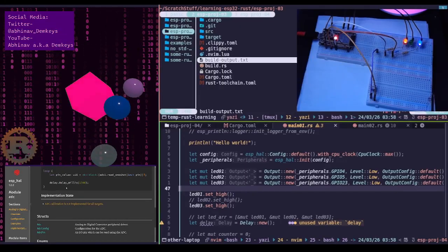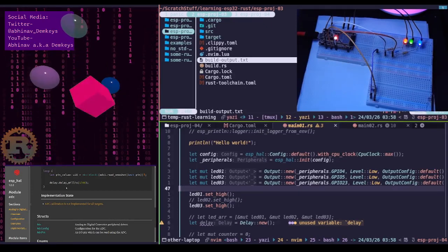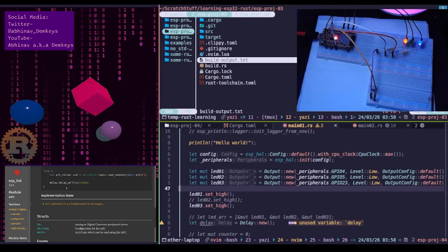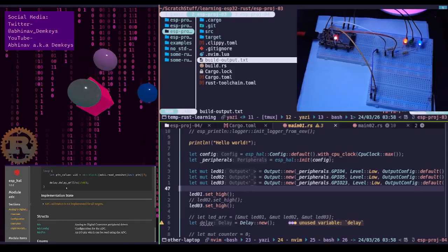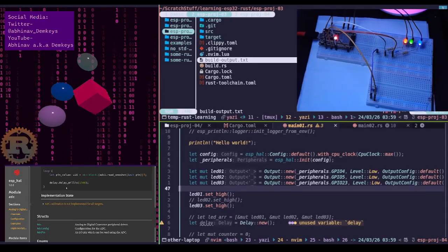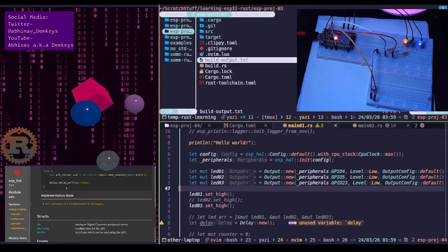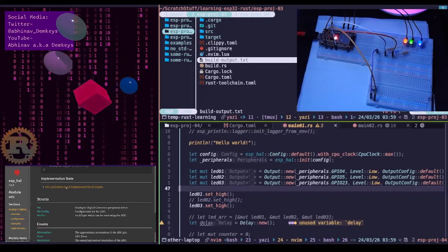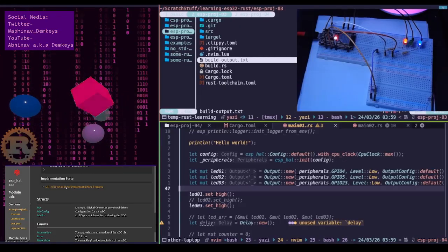wouldn't this just mean that I need to test out min and max values myself? Like hook up a potentiometer to VCC and ground, and the middle pin goes to ADC, and then I turn the potentiometer all the way to one side and note down the value there, and then turn it all the way to the other side and note down the value there. The smallest of those values is the minimum value, and the largest is the maximum value.